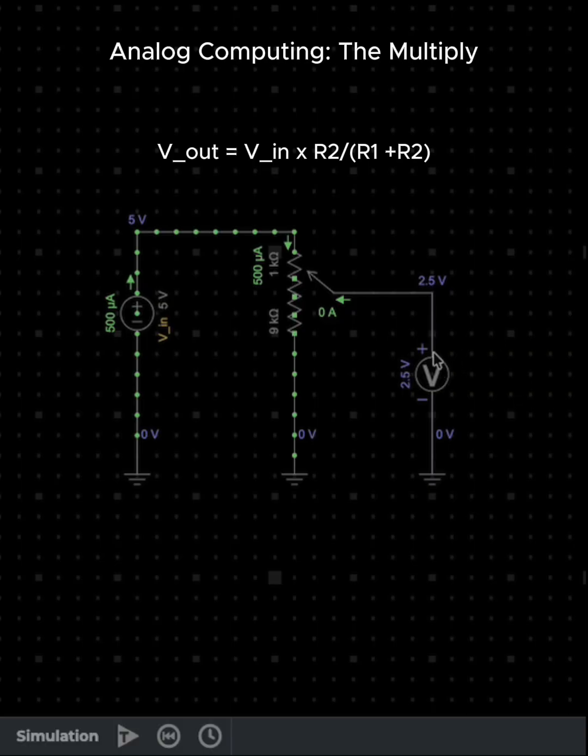As we can see, when the wiper splits the potentiometer, you get two resistances in series. In the current setup, it is 1 kilo ohm here, and 9 here. The other resistors, that is R1 and R2, we can call them here. The top one is 1K and the bottom one is 9K. Let's run the simulation now and see what this V out will be.